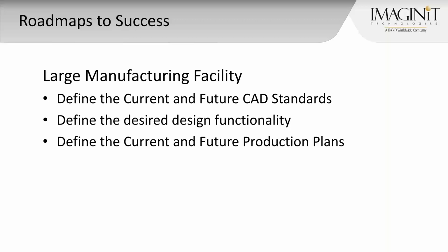The other thing that we found out is line types. The custom line types need to be made firsthand. The other question that we have is, well, can I translate my drawings and then go from paper space into model space? And the answer is no, not during the translation. Again, one-to-one translation. You can't make it do something that wasn't in one environment into the other environment. That being said, there are script routines that will, once that has happened, you can run those and it can create your paper space, model space.